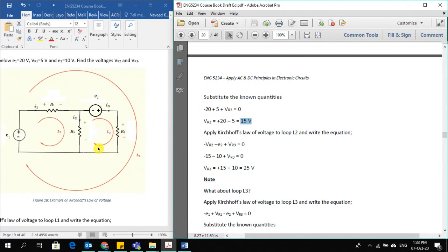So simply follow the same current flow which is given in the circuit diagram, clockwise. So start over from here. This resistor R2, you see the negative sign first. Look at this arrow. So you will write minus VR2. Voltage on this as minus. So minus VR2, I have written my first term. Then I will move along clockwise and I come across voltage source E2 and I look at the negative sign first. I will write minus E2. So minus E2 is written here.